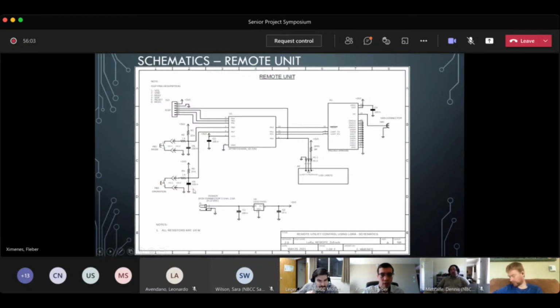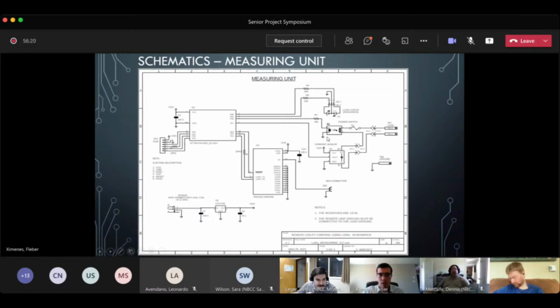Okay. Exactly. And I see for your A1 IC, your pin 6 and 7, there's a little blip there too. Yes, there is. And on your other schematic, there were a couple. They're just minor flaws, but to me they stand out. I see where your power jack is coming in, C7. Yes. It's not lined up properly there. Your VDD for your A3, I see they're not lining up there either. Maybe you didn't notice those things, but I noticed them right off the bat. So just keep your formatting clean, I guess.